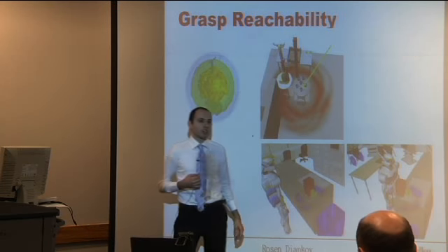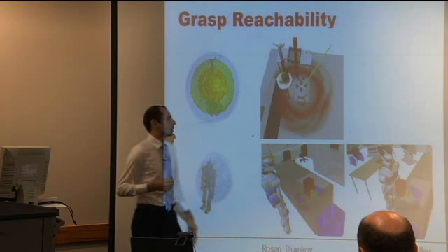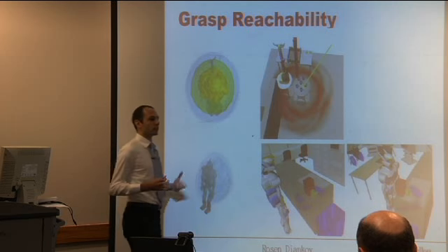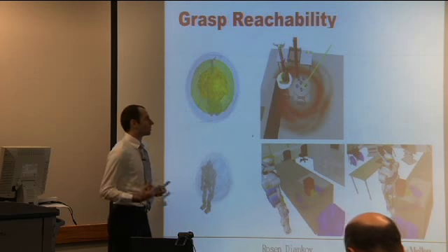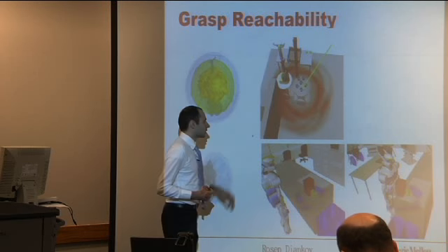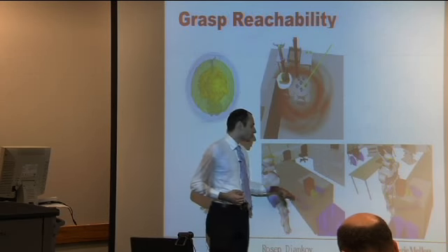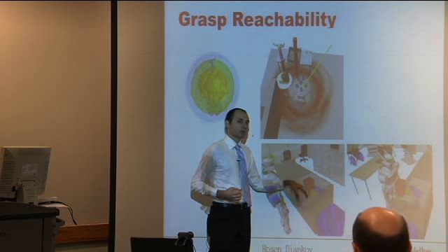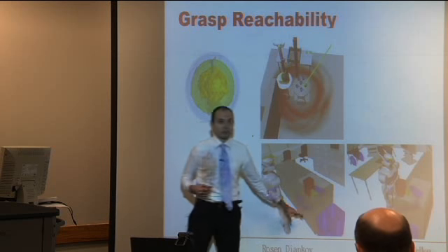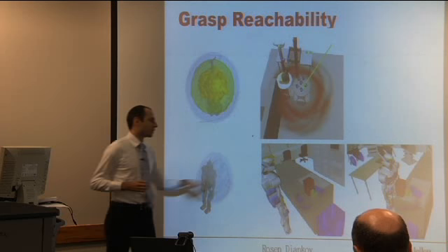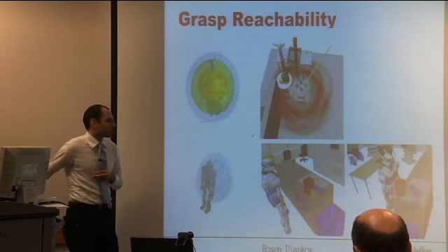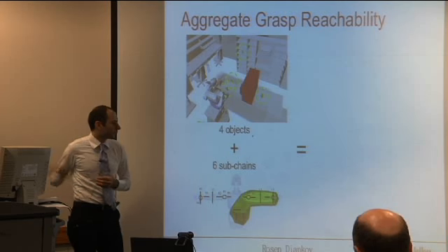We also introduced a concept of grasp reachability, where we can combine grasp sets for a target object and the inverse reachability to form an aggregate map that will tell us where the robot base should be placed in order to find a grasp for this object in the current environment. And we show ways of how to compute this fast and validate collision obstacles, etc. Furthermore,